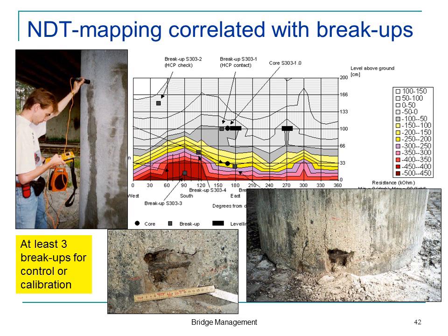There's only one safe way of assessing the condition of the reinforcement. That is, remove the concrete and have a look at it. It's the only thing that always works. Of course, we're not going to remove the cover on all the reinforcement bars. That would be stupid. We make a mapping, and then we open up 2 or 3 places.